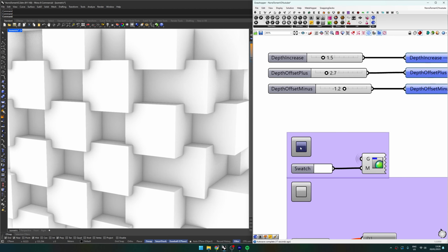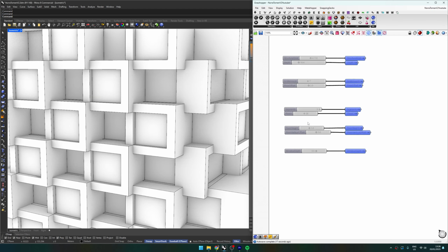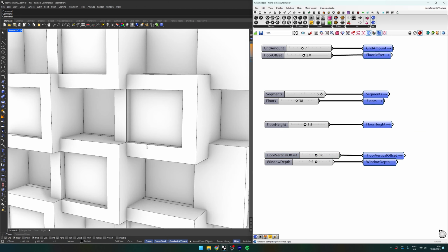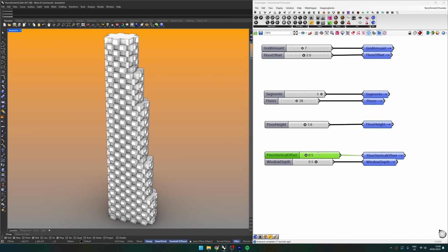For that, let's also use a different preview. Let's go to this preview, the Boolean operation preview. Basically here we have 2 sets of parameters. One says something about the height here. So let's change this to 0.5. It gives a different form language. We can also make it 1 to make the bezels of the windows very thick. It basically dictates where the window starts.